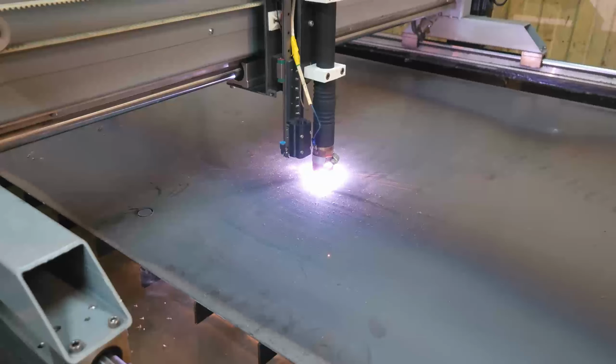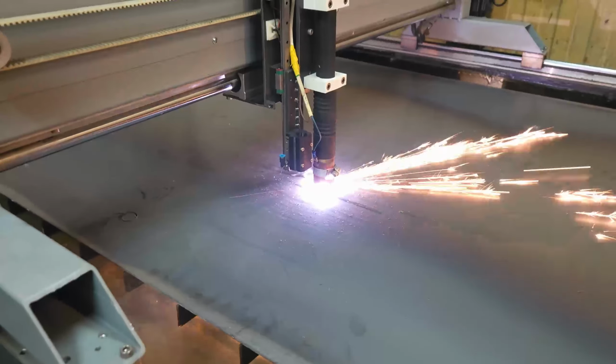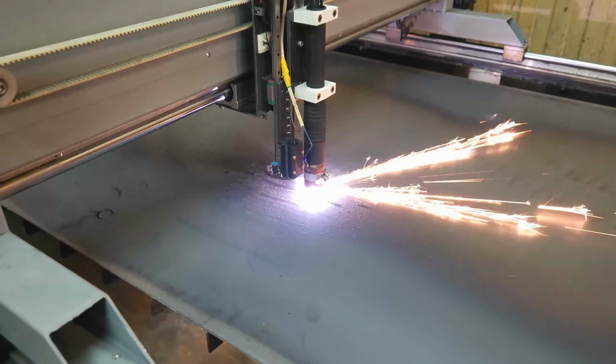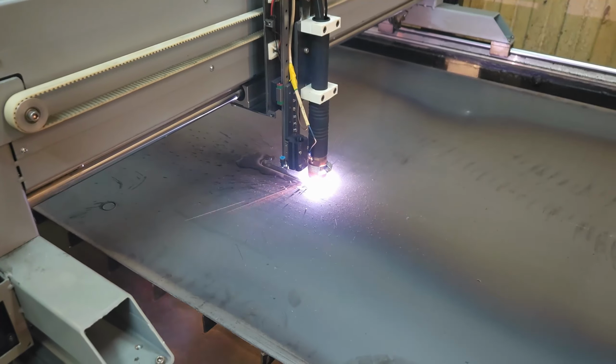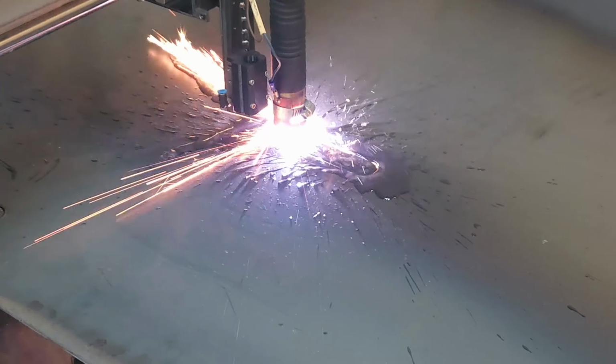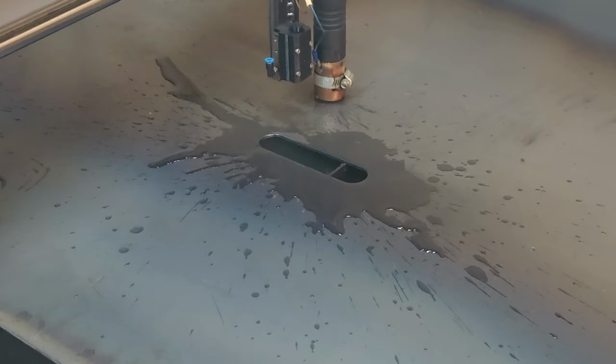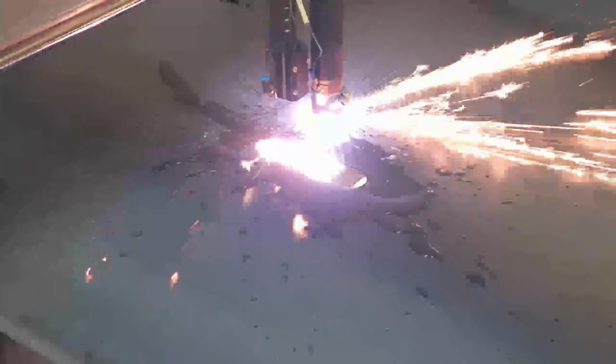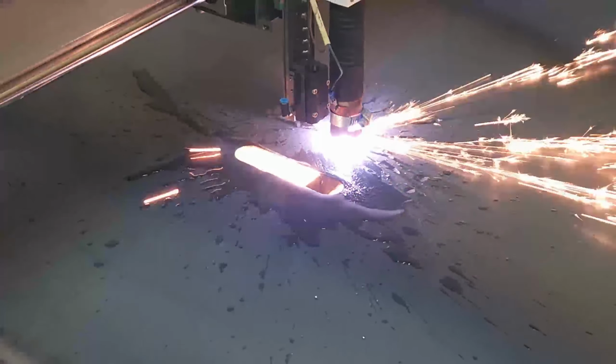There are three main aspects of plasma cutting: cutting speed, arc current, and compressed air quality. Each one is as important as the others, and you have to keep them all in mind when changing one of them. You cannot set the cutting speed based only on the thickness of the material. Arc current also has to be set correctly.